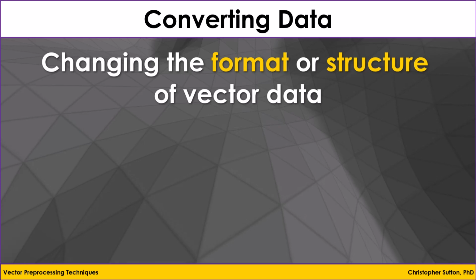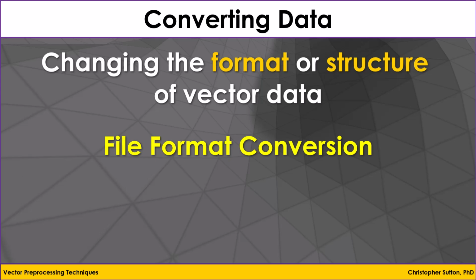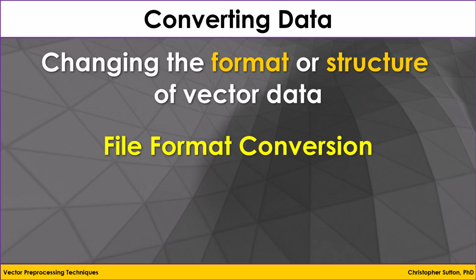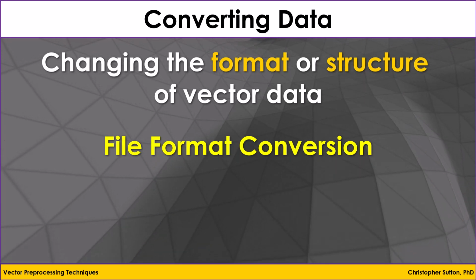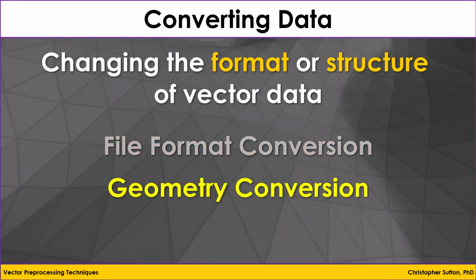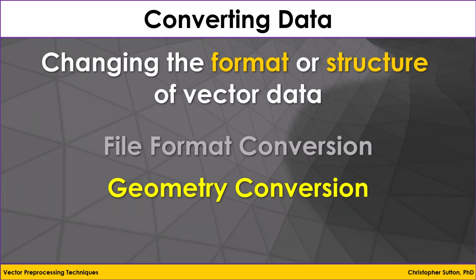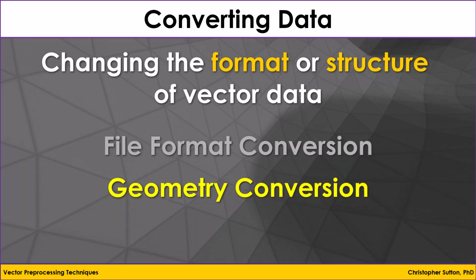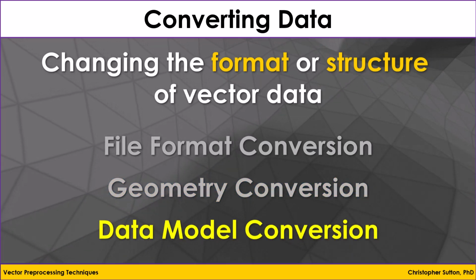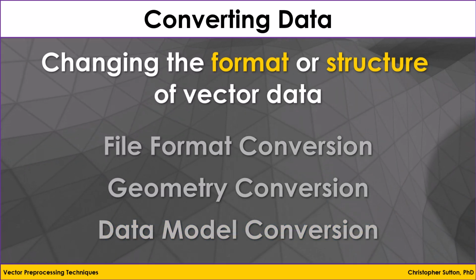Finally, we might convert data, which is changing the format or structure of vector data. This can include file format conversion, where we convert vector data between different vector file formats. For example, shapefiles, geopackages, GeoJSONs, CAD files, KMZ files, etc. There are geometry conversions, where we transform data between different vector models. For example, transforming a point shapefile or feature class to lines, or polygons to lines. And finally, there's data model conversion, which is the conversion of vector data to raster data or raster data to vector data.